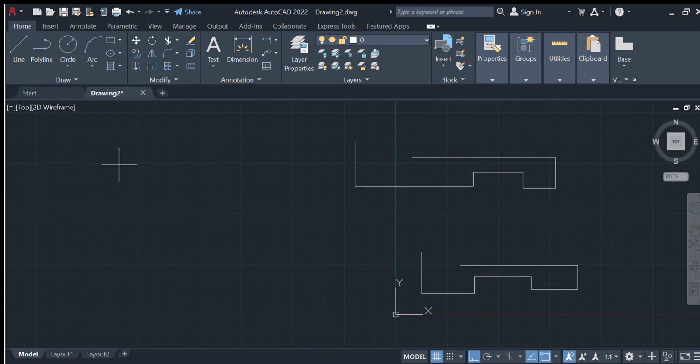Now that it is telling you to specify start point, remember we have two numbers attached to that specify first point prompt showing on your screen, and as you move your cursor, the values change. Those two numbers represent your x and y axis. So how do we input values into our x and y axis?